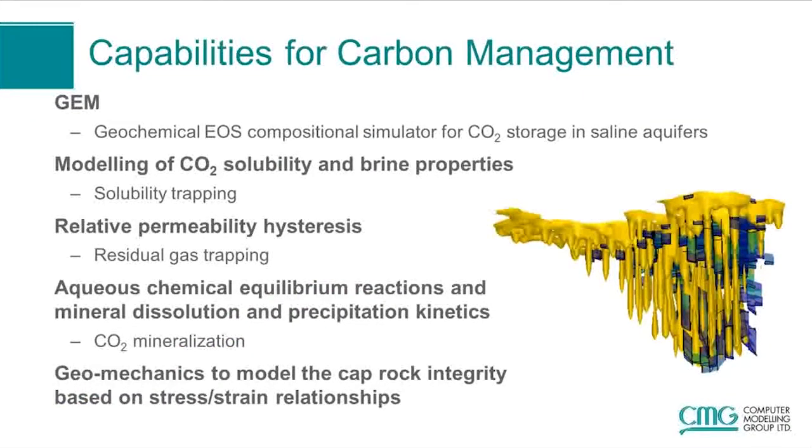So there are some capabilities for carbon management in GEM. As I mentioned before, GEM is a geochemical equation of state compositional simulator. Therefore, GEM can be used for carbon dioxide storage in saline aquifers, and GEM can capture all the mechanisms involved in carbon dioxide storage. Some of the mechanisms are solubility trapping, residual gas trapping or hydrodynamic trapping, and carbon dioxide mineralization.